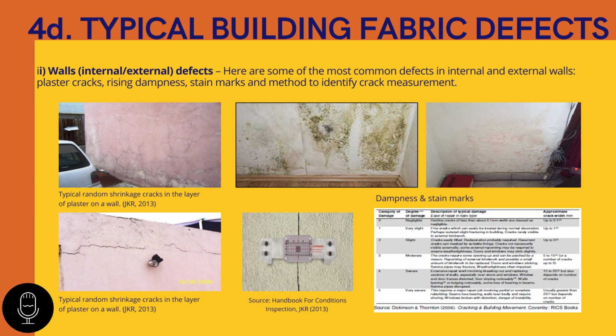How are we going to monitor crack width? Normally, we use a simple instrument, which is a telltale crack monitor, to monitor crack development, as shown in the photos.